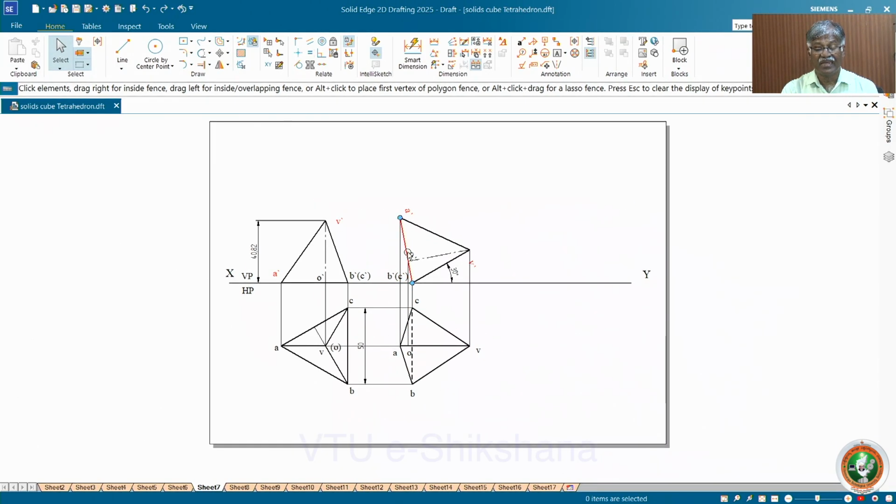Now you see the completion of the top view. If you look from this direction, the farthest item from you is BC. BC is not visible. Then the boundary is completely dark. That's all. And then what about this line? This line is an invisible surface, visible line. See, the farthest item from you is this. The number of lines connecting to that are not visible, but all are boundary lines.